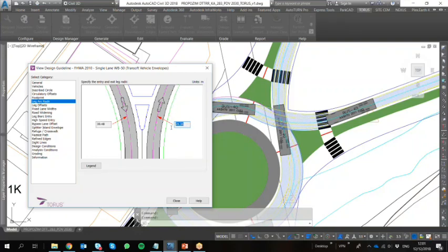What we define is the radius for the center path of the vehicle, and based on that, and based on the design vehicle, we calculate the vehicle swept path. There's going to be an off tracking here, so to the inside of the curve, the rear end of the vehicle will tend to lean in more. And then, based on the calculated swept path, by applying an offset, we calculate the road edge.